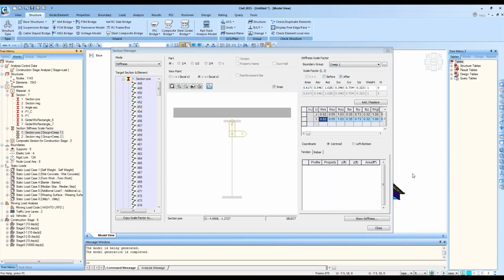And another hint here is, another frequently asked question is, can you reflect the steel deterioration or corrosion in MIDAS? Common questions for the engineers that are working on the load rating projects. Again, civil can cover the load rating too. So in order to reflect the deterioration or corrosion, you can also utilize this section stiffness scale factor. So as much as the corrosion is affecting the section strength, you can use this scale factor to bring down the full stiffness of the section.